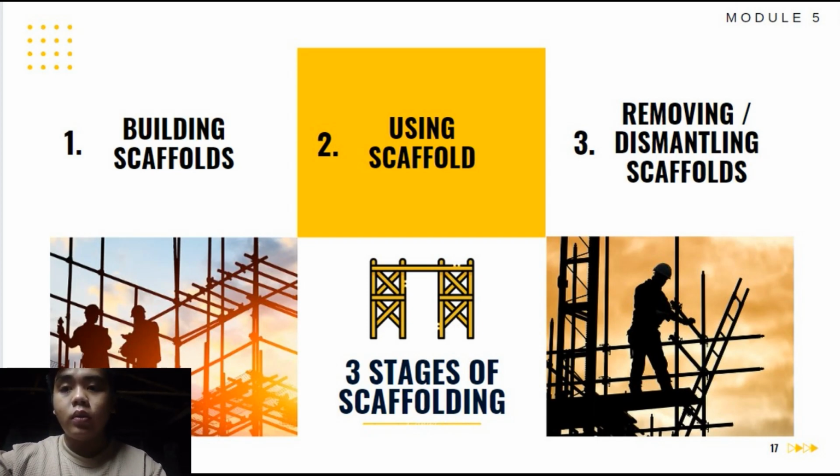Workers should wear a safety harness and lanyard tied to a secure anchor before attempting to loosen, knock, or jump parts. Do not hammer or pry apart scaffold components. Do not throw scaffold components.